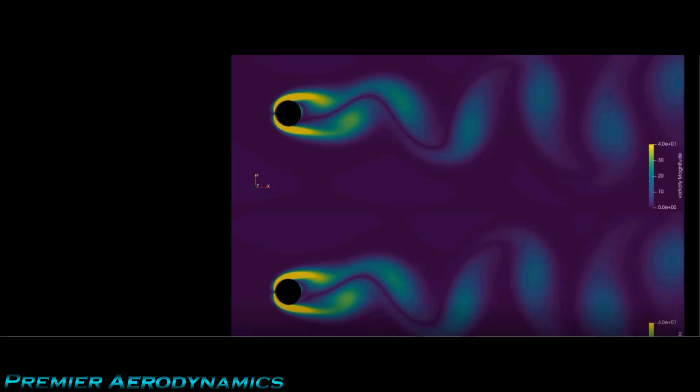And you go, okay, so I'm going to go into the wind tunnel, and I want to get my wind speed to get to 135 pascals in the dynamic pressure when I put my pitot-static tube in there. So I want the difference between the static part and the pitot part to be 135. When I get there, I know the velocity is then 15 meters per second. Except it's not.